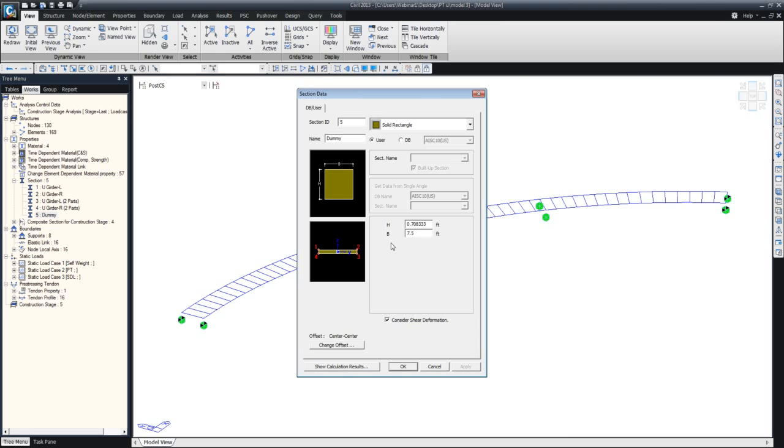So engineers usually try to monitor the bending moment distribution between the two girders by reducing the stiffness, and when they come to a point that the bending moment in an individual girder is not reducing after a certain point, that means it is not being shared any longer with the adjacent girders, they come to this limit on the width. And so this is the standard practice.